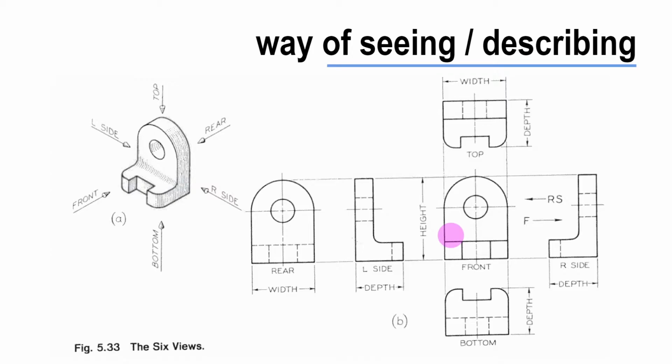So the front view can tell us the width and the height, but it's missing information related to depth. Think too, just to fast forward a bit, of a set of plans, where I'm looking at the front of a building. In a set of plans, I'd be able to see that there's a porch up here and then the house, but the front view of that plan, or that elevation, wouldn't tell us how far back the house is and how far forward the porch comes.